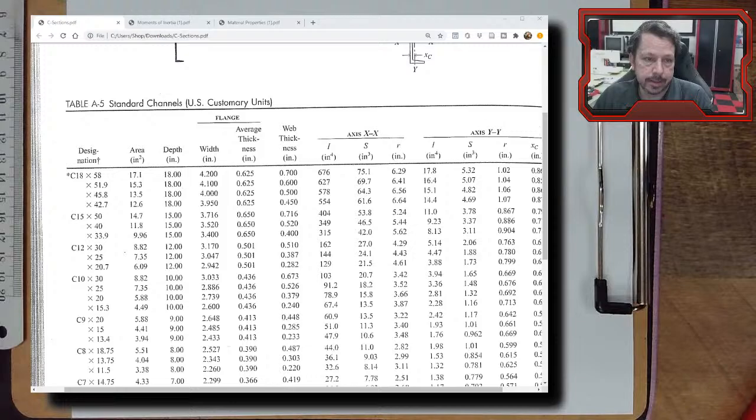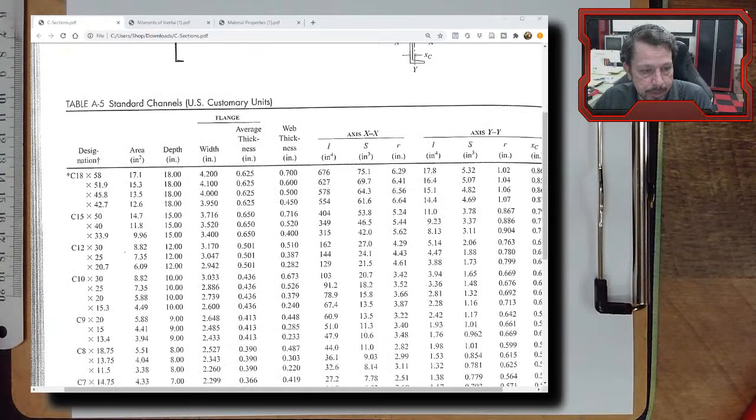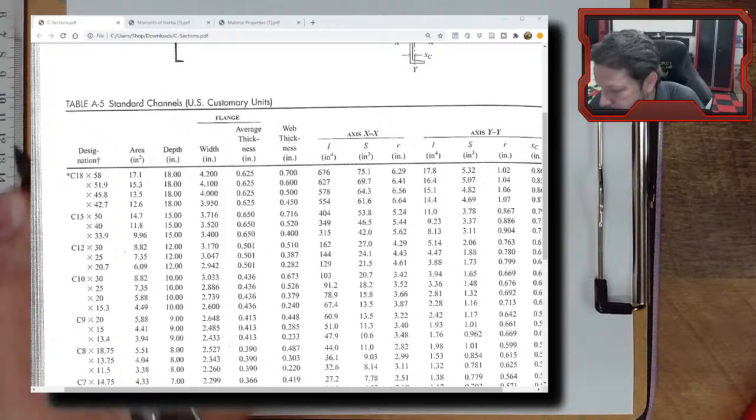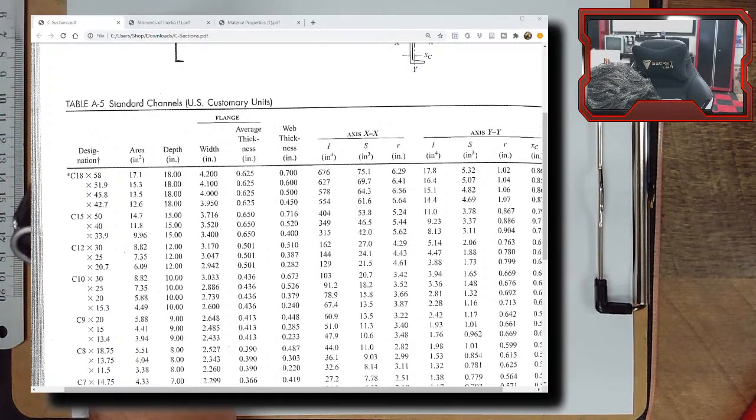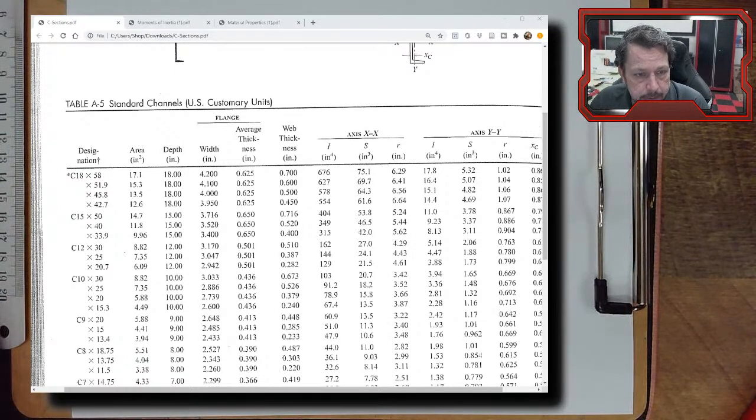We're going to need, well, we don't need it, but this width of the flange, that talks about how far these little flanges stick out. And it says for C10 by 30, that's 3.033. I'm going to call that dimension H, just because I want to label it as a variable in our picture. So 3.033 inches. We don't necessarily need the flange thickness or the web thickness.